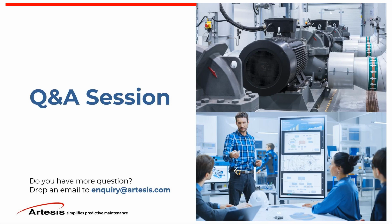Can we detect lack of or poor lubrication issues early? Yes, you can actually detect lubrication issues. We have some cases. Of course, that will show itself as bearing faults. It will be detected that you have a bearing issue, and you can do detailed bearing analysis when you enter the bearing specs into the spectrum. You can look at the inner race, outer race, cage, or ball spin frequencies. And if you look deeper, you can see whether it's actually because of the lubrication or not.